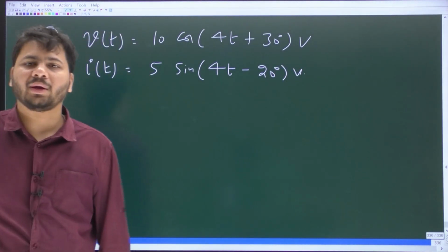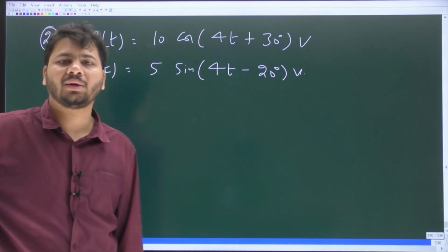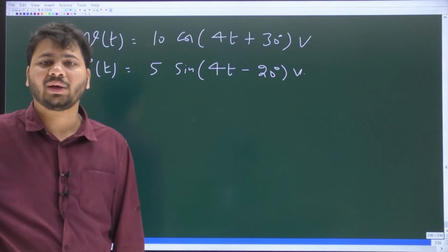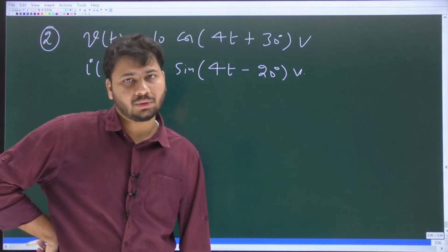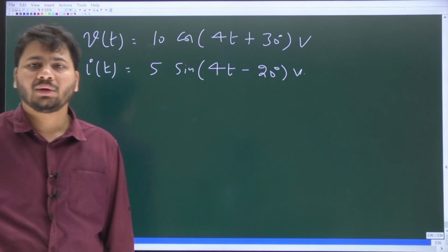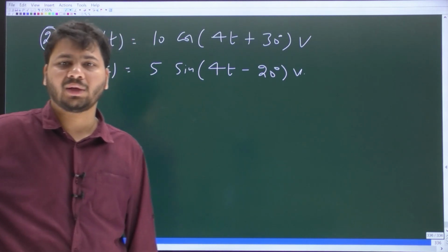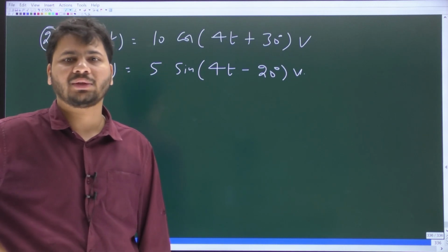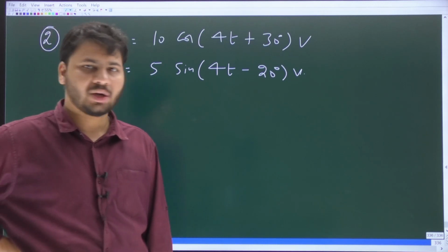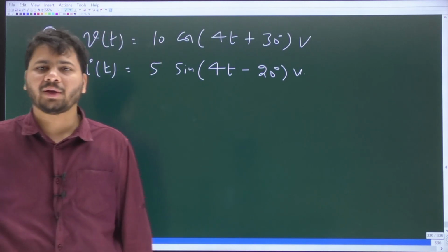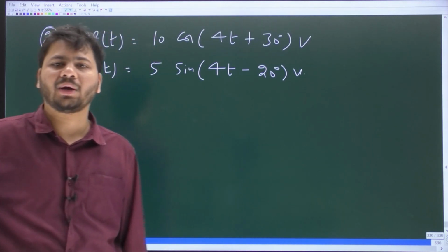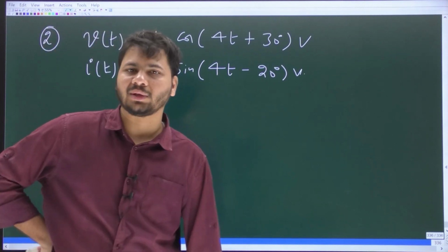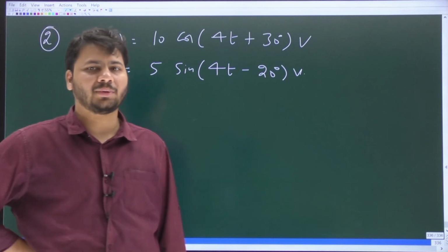So this time, can we say, or can we find out, which one is leading and which one is lagging? Just say yes or no. Yes, because both are at the same frequency. If you want to take the phase difference between two quantities, the only requirement is that both should be at the same frequency. This time, definitely you can say which one is leading and which one is lagging.